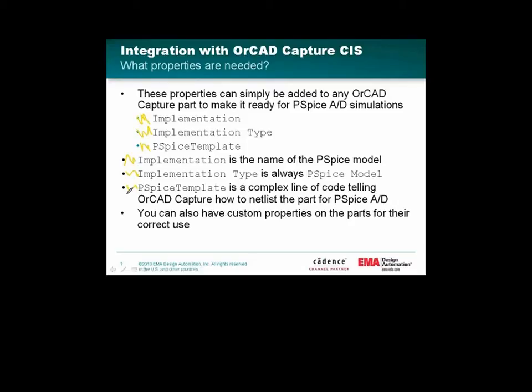The benefit of managing all this information in your database is that if you have a design that's just done in Capture, but you want to make it PSpice intelligent so you can simulate it, you can just quickly sync all this information into your schematic, and then going forward, you now have your Capture designs turned into PSpice-ready Capture designs.